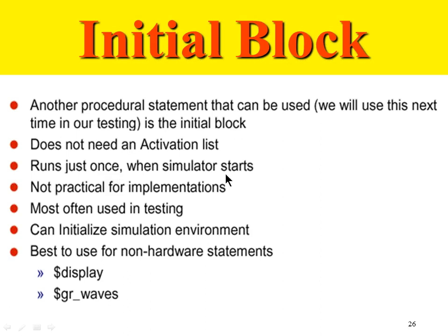Verilog was actually developed, as we have seen earlier, only as a simulation language. It was only afterwards, in the mid or late 90s, when synthesis tools were developed and Verilog could be converted to hardware. The initial block will run only once when the simulator starts, as far as software simulation goes, or it will run once when the hardware design starts or initializes.